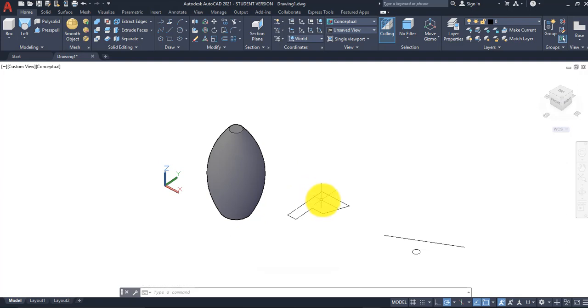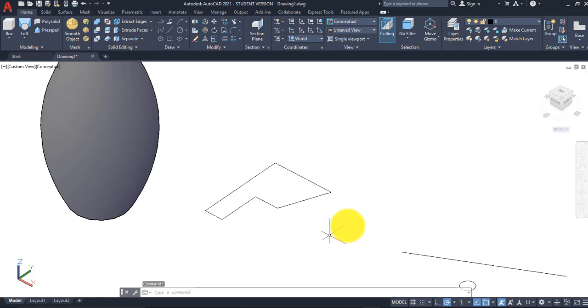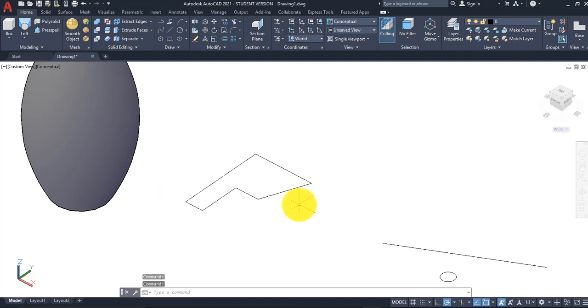So we created geometry here for the revolve, and what I'd like to do is copy this so that I can show you that if we revolve just the 2D geometry, the revolve will be empty. We're going to fill it in with a solid so that the revolve will be a solid shape. So let's start by copying this, whatever shape it is that you created when we created it in the 2D top view.